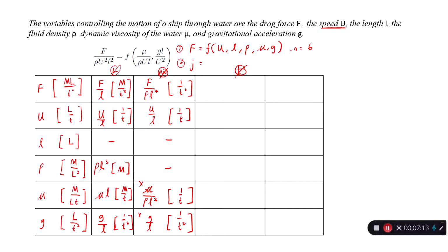Okay, actually if you did not have this equation, you tend to choose a simpler one, maybe gravity over L, because gravity is definitely a constant, whereas u probably is not a constant. But you will see that if we chose g over L, we cannot get this version, and therefore this version actually represents existing constants in fluid mechanics, existing numbers.